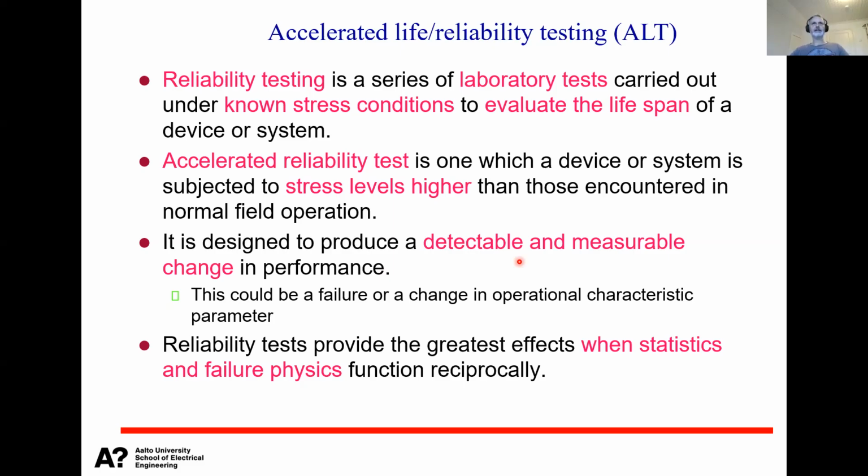And accelerated naturally means that you increase the stress levels higher than those the system typically faces in normal operational conditions. So you use higher stresses: higher temperatures, lower temperatures, higher vibrations, higher mechanical loads, higher voltages, higher powers, higher currents. The stress you use is higher than what the product would see in normal operation.